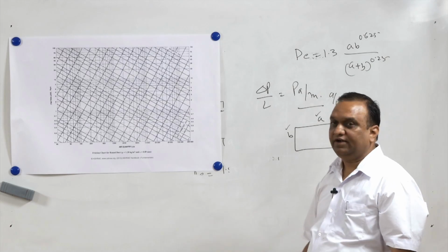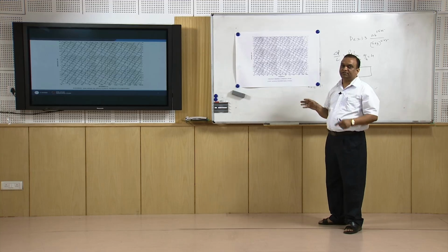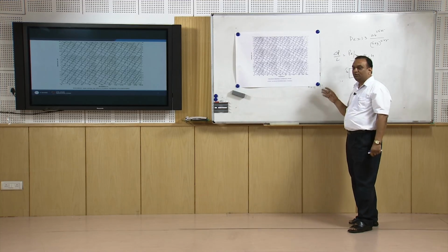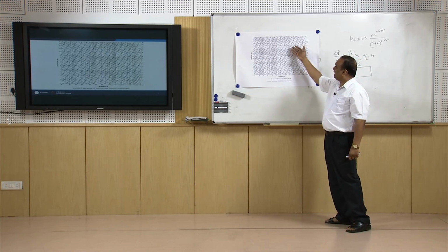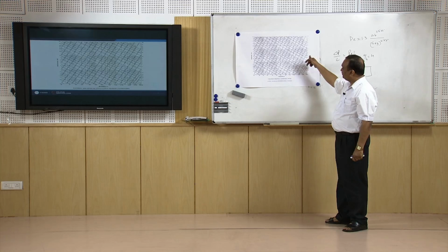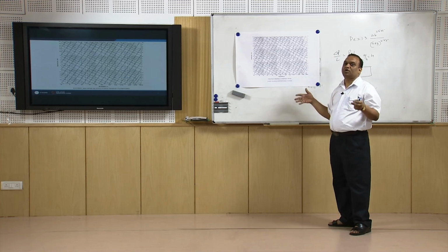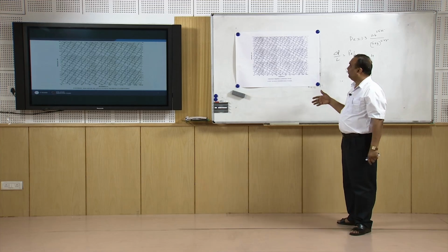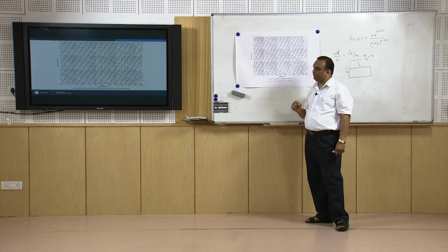In a network of ducts, there are going to be ducts of different length and different discharge. For that network of ducts, we can find the diameter of each individual duct using this chart. In addition to that, using this chart, we can find the total pressure drop in the system, which will help us in deciding the size of the air handling unit.